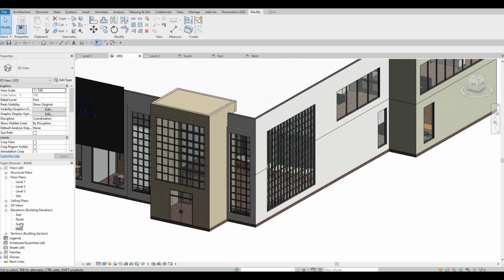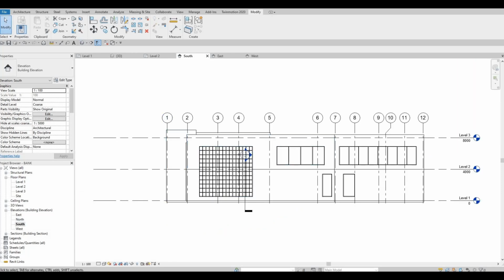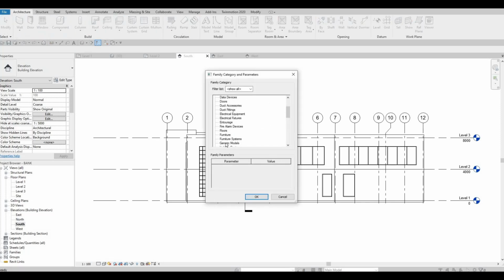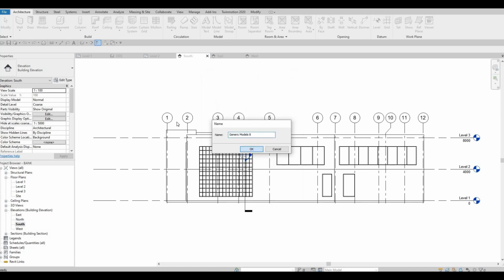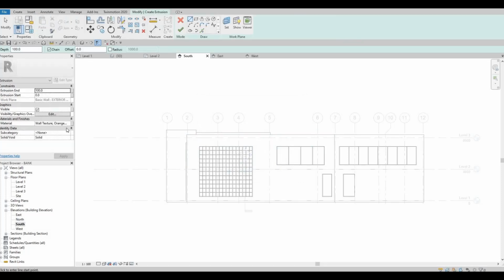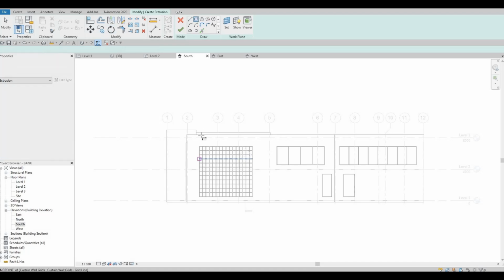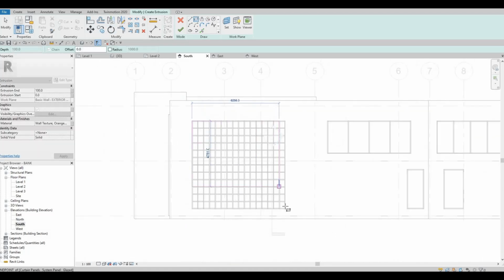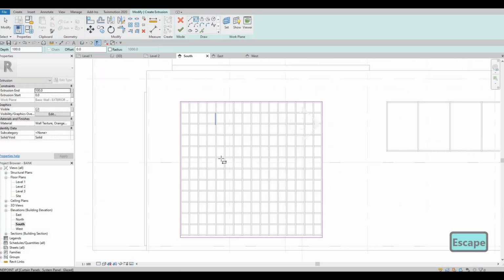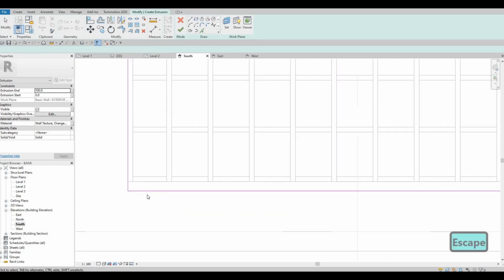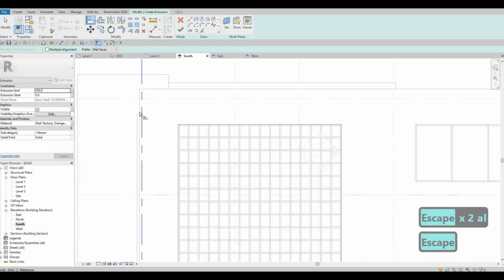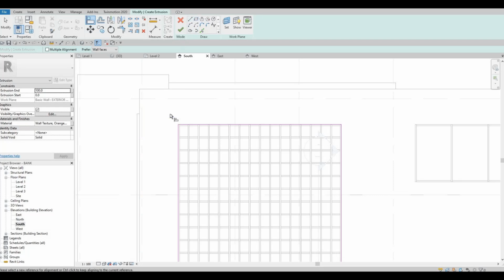And then we're going to just do it right here. Lastly, so this will be our south elevation, and then we're quickly just going to model in place and then add the same thing. Extrusion, pick a plane, and then this wall right here, and then same thing. It's already set up, so we don't need to worry about that. What I just want to do here is to make sure this one should align right here at the top. I want to align it from the top right here.